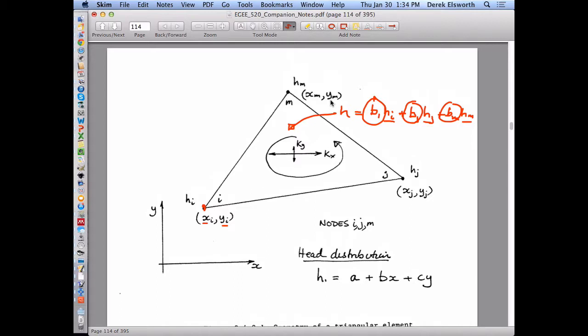Imagine we have two triangles, one next to the other, sharing a node. If we have a constant gradient in each element, where different elements may have a different gradient, would that mean the same node has two gradients? The element would have two different gradients as you go across it. Let me draw what I think you're talking about. If you have an element here, and an element here, and you draw a section across, then you can potentially have two different gradients, and that's exactly right. If we drew this pressure, I can't draw it very well, you could have a gradient in this element here, and it could change to some other magnitude as it goes here, if this is pressure versus location.